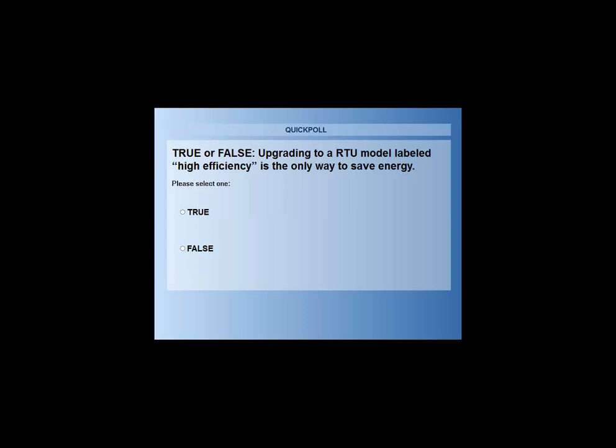And then when the building goes occupied, say whatever, 7 a.m., then you need to ventilate for the code-required square footage portion, and then you need to also ventilate for the code-required per person portion, assuming the people are there and breathing and recognized by the CO2 sensor. But at nighttime, you can shut it all the way down to 0, assuming the building's unoccupied at night, obviously. If you're a 911 center, then there is no unoccupied time.